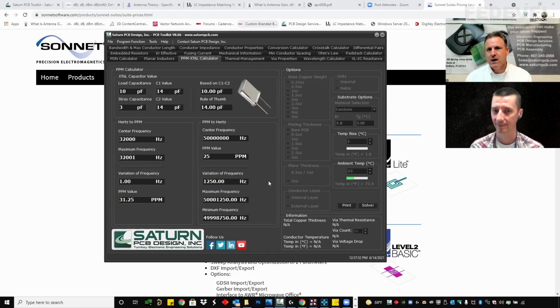We laid this thing out and it wouldn't work. We spent two months trying to figure out why this thing wouldn't receive. One day I decided to look at one of the crystals that was driving the receiver chip. I hooked it up to the spectrum analyzer, put my span down to like hertz, and noticed that the crystal was way off.